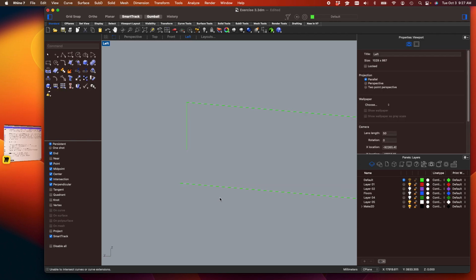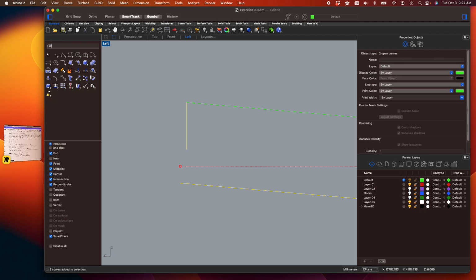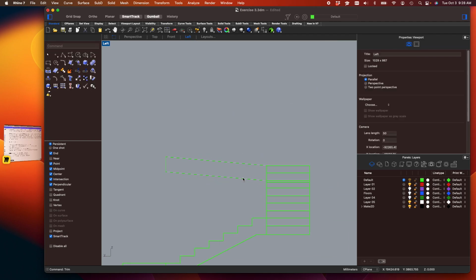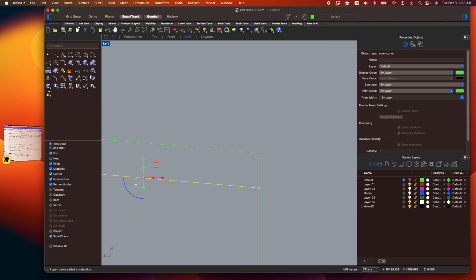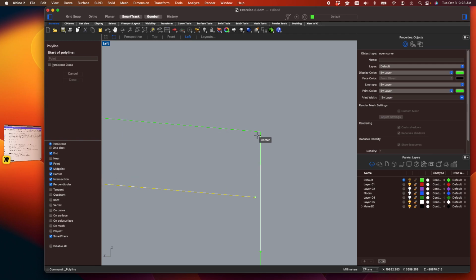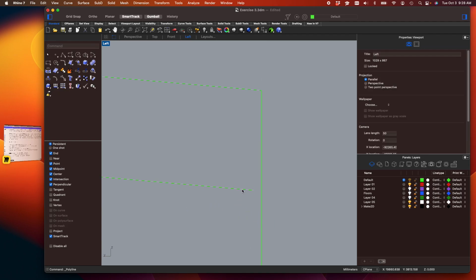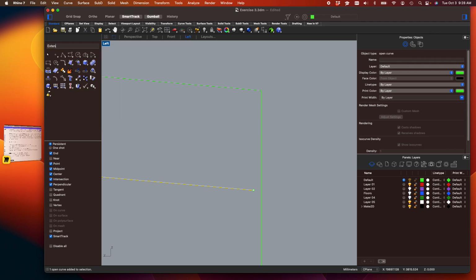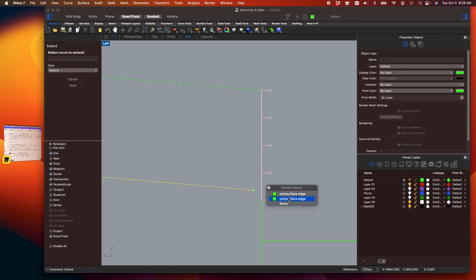It should. Well, I guess we can extend too. Not sure why it's not working. We'll extend that one instead and just trim. Not a big deal. There's our profile. It looks like we're still missing 1 line. So it definitely takes a little bit of time. Can't really see that line because it's in another, but let's go ahead and extend that one. We'll choose that line. I guess we can choose the polysurface edge too, not a big deal.